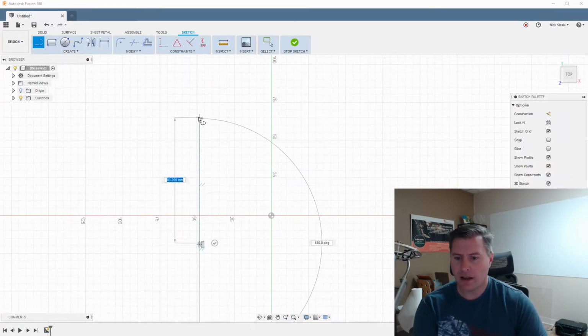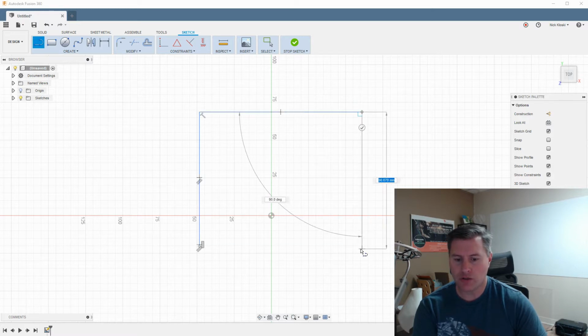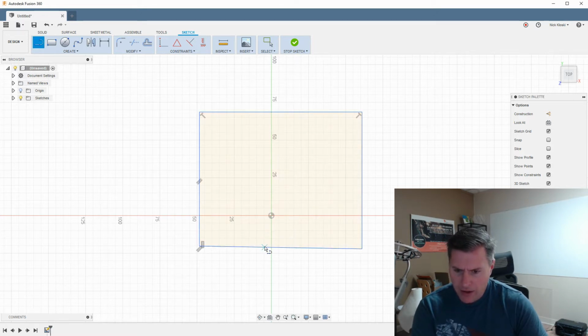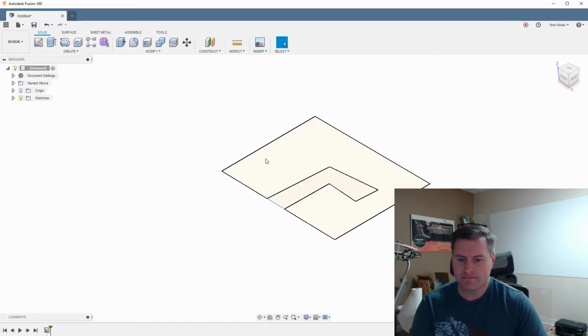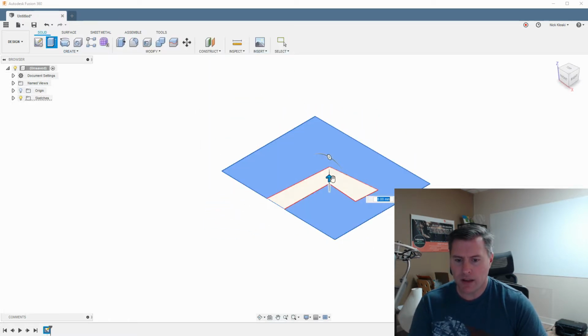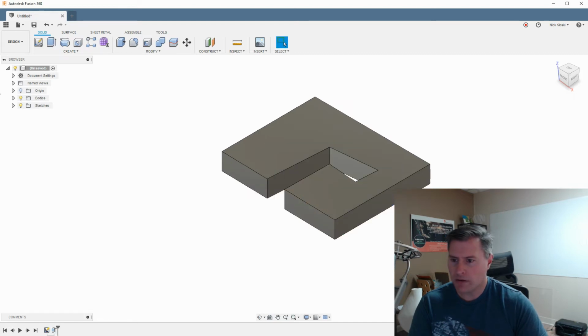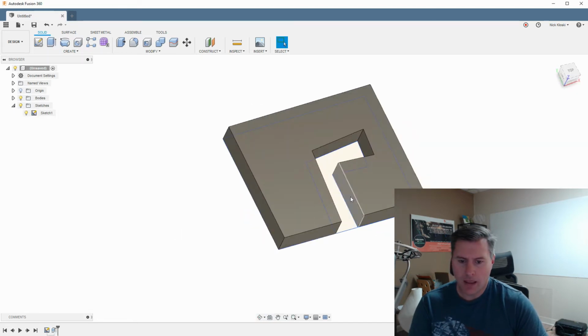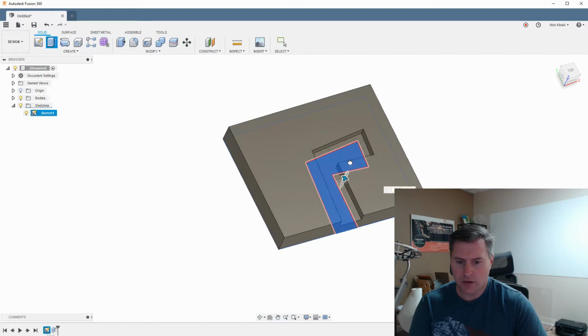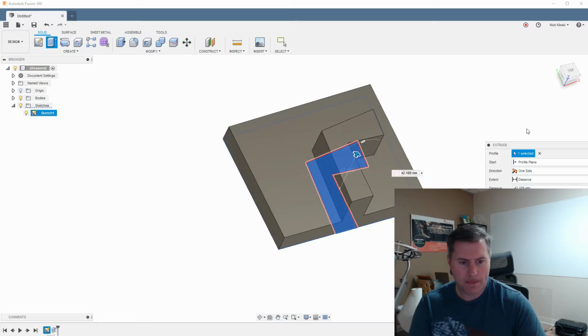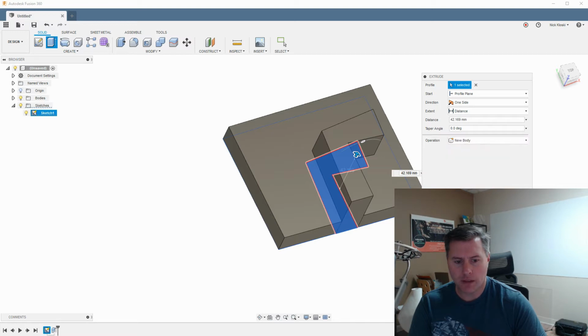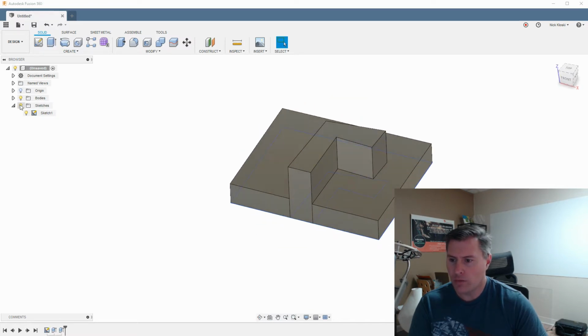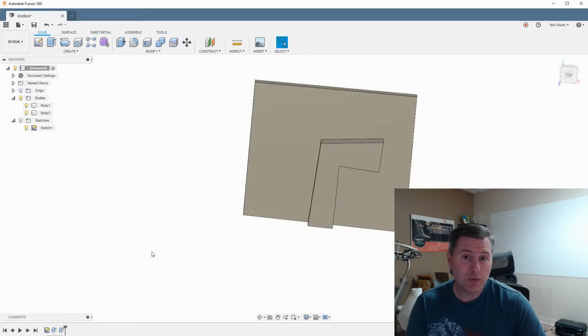If I created, like the example on his website, a box like this, and I created something that would be cut out of that box like this, so I pop this up into a shape, and then I pop this up into another shape as a new body like that. Great. We have two bodies right here, as you can see, number 1 and number 2. If I tried to print this, it would just not work.